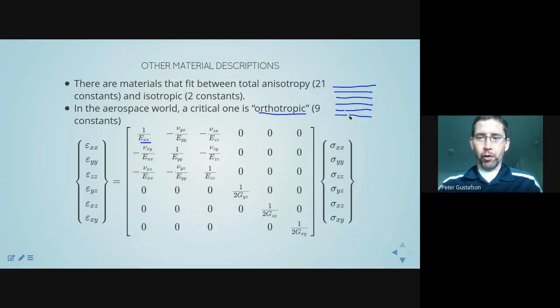By the way, these are bound together by what's called matrix. The matrix is typically an epoxy. So it's like a glue, essentially, that's holding all those fibers together. So if you're pulling in the x direction, it's going to be relatively stiff because those stiff, strong fibers are aligned with that direction.